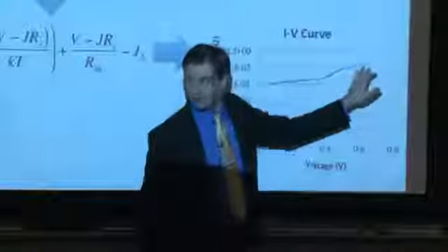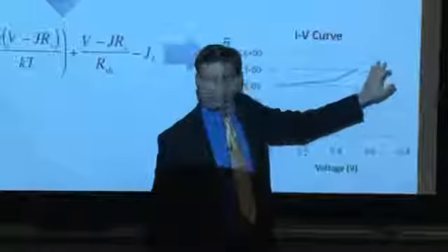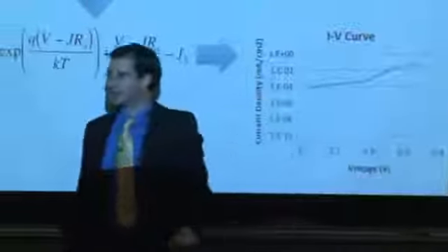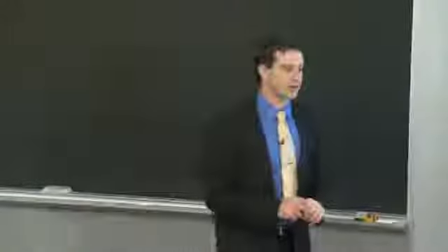And likewise, you'll notice that the shunt resistance really isn't impacting you up here. The shunt resistance really isn't impacting you at higher forward bias conditions. That's mostly series resistance and the illumination current that's overwhelming any shunt pathway.